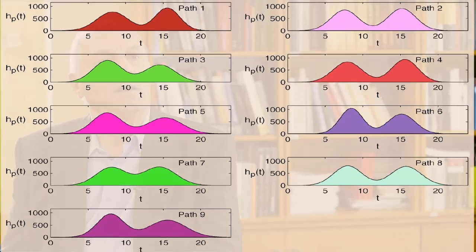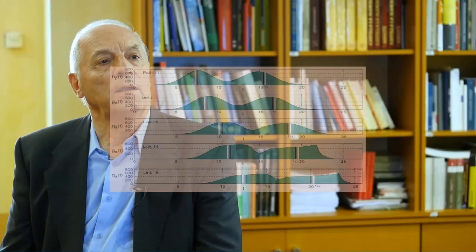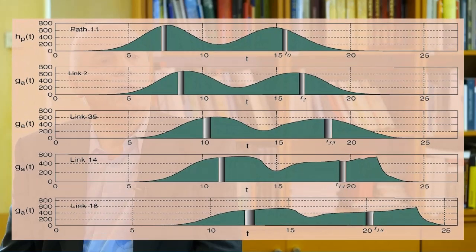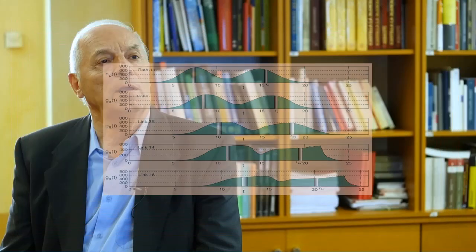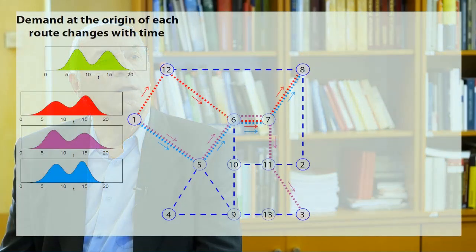Once the flows pertaining to different paths enter the network and reach a link, they combine together and produce combined or mixed waves, whose shapes are obtained taking into account the link capacities and the total demand at any time, and provide us with very useful information. In this animation, you can see how the traffic flow waves deform when traveling along the different links in a given path due to traffic mixing and congestion, and we illustrate how these waves look like.